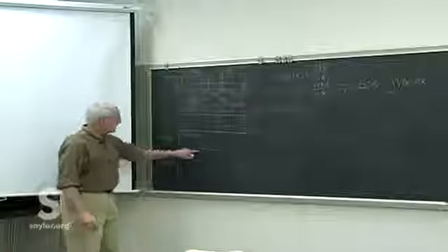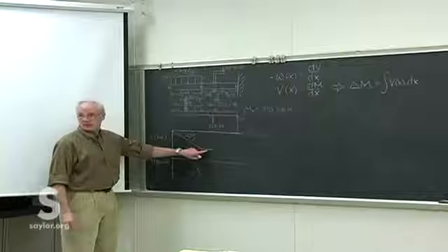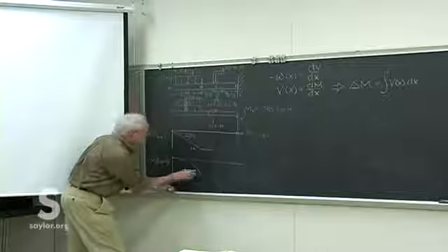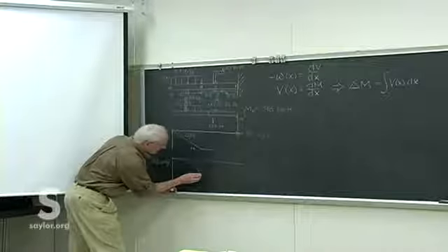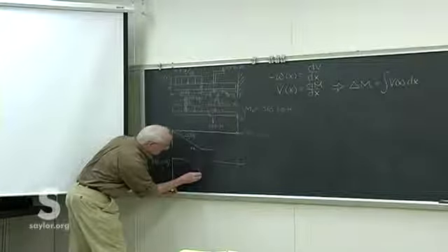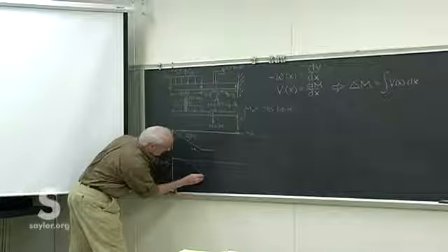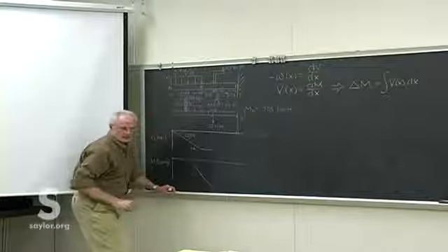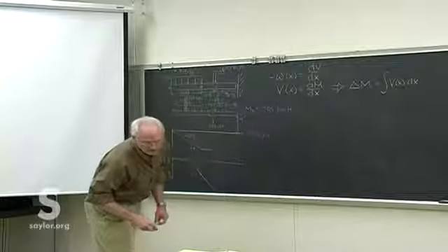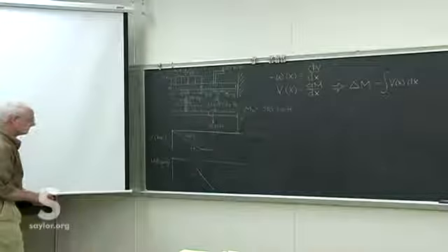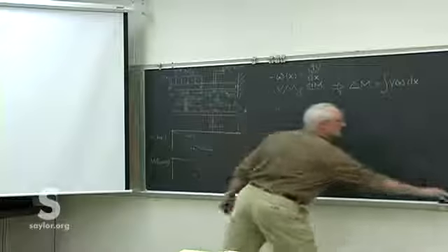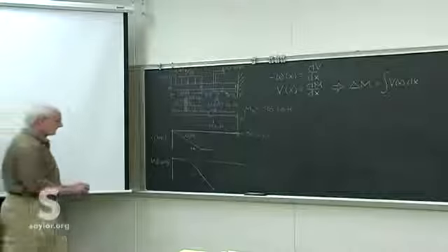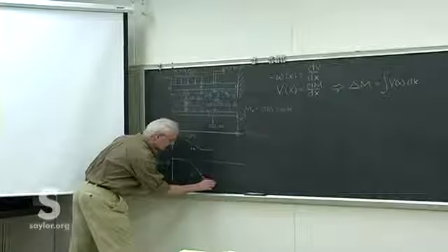We know that the moment now has a slope of minus 24 from there on, and the slope is continuous, so we continue the line straight where the slope left off. I think we're going to, as often happens, have to redo this drawing, just because we're running out of space here at the bottom of the board.